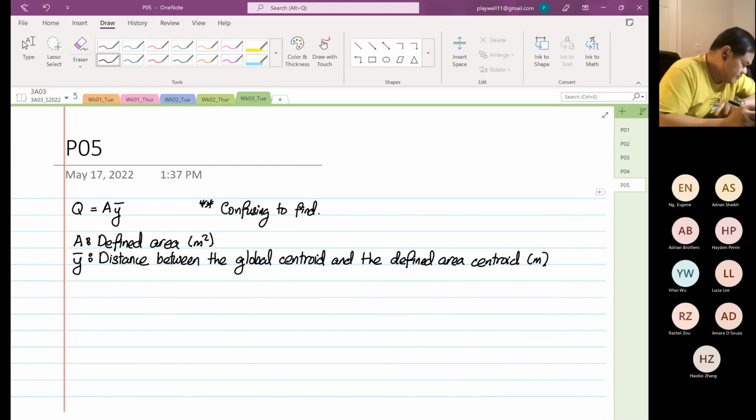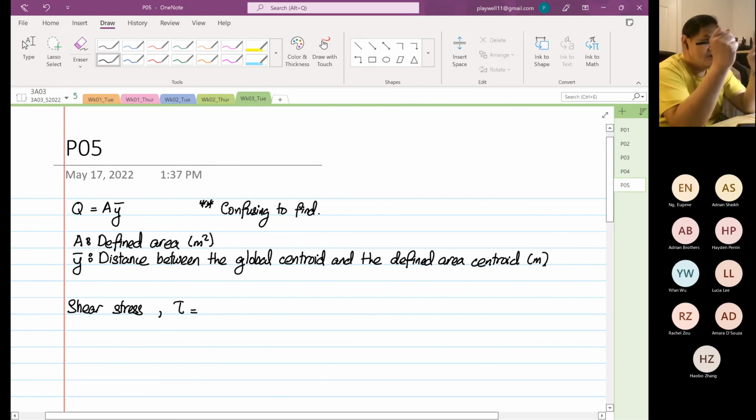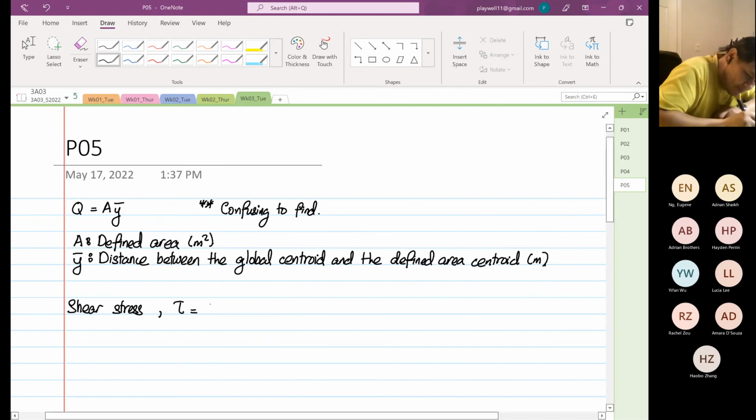Now, more importantly, is the shear stress. The shear stress is equal to tau is equal to V. I will write both components, so you can have y or z. So Vy, and I want you to look at the formula. So Vy over Iz